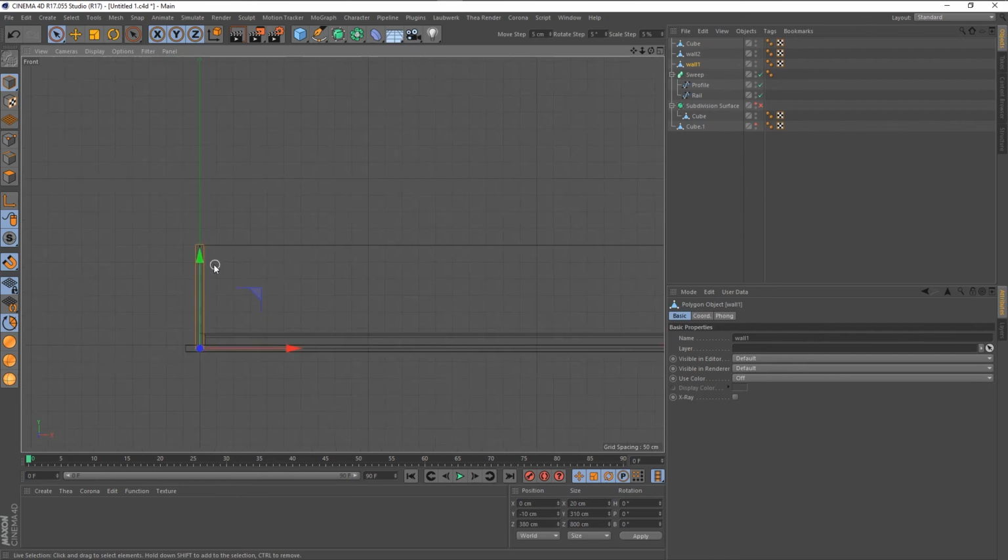All right, so you're going to use this axis tool, which is shortcut L, and you're going to use your snaps and your quantizing to be able to set your position for that axis. And the quick way to grab snapping points is hit V and then hover over the snaps, and then we should definitely use vertex snap. And like if we wanted to move this to a different vertex, it'll snap to that vertex for this one, so on and so forth.